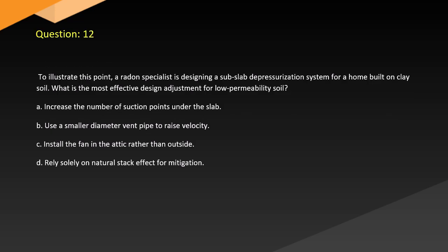Question 12. To illustrate this point, a radon specialist is designing a sub-slab depressurization system for a home built on clay soil. What is the most effective design adjustment for low permeability soil? A. Increase the number of suction points under the slab. B. Use a smaller diameter vent pipe to raise velocity. C. Install the fan in the attic rather than outside. D. Rely solely on natural stack effect for mitigation.